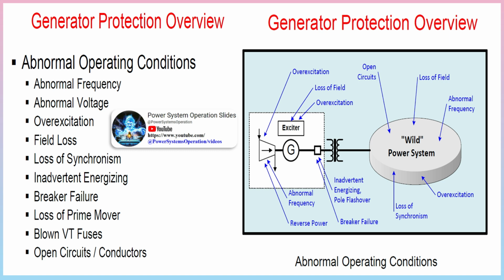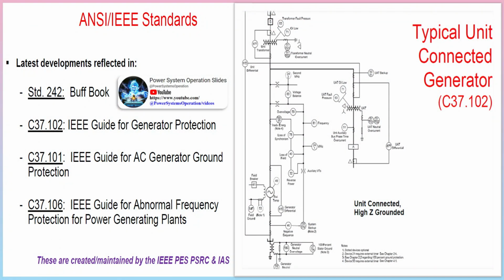Types of generator grounding: low impedance, good ground source. The lower the R, the better the ground source. The lower the R, the more damage to the generator on an internal ground fault. It can get expensive as resistor voltage rating goes up. The generator will be damaged on an internal ground fault current, typically 200 to 400 A.